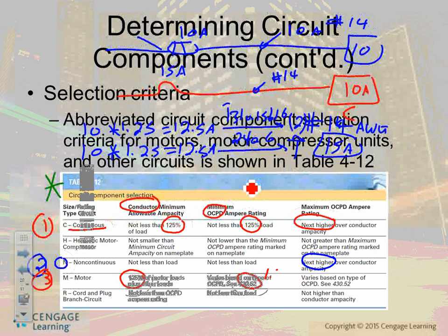If it's a fuse, 1.75 or 3, or 2.5, these are all multipliers. These are the most common ones that we use. 3 multipliers. 1.75, you guys used it with Chase. That's a dual element time delay fuse. If it's a non-time delay fuse, 3, and if it's a circuit breaker, 2.5. Please highlight this table, table 430.52. We'll be working on that one too, guys. Okay? Now, this is 430.52, table 430.52.